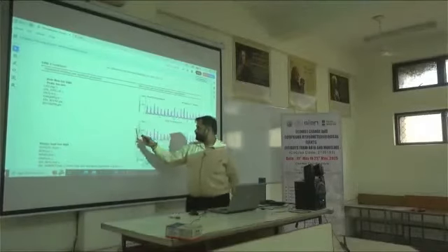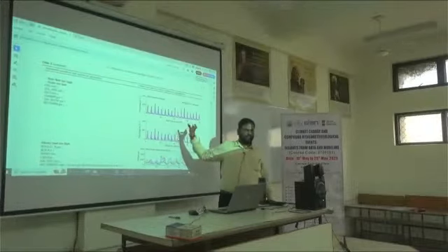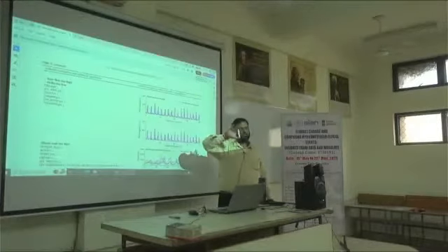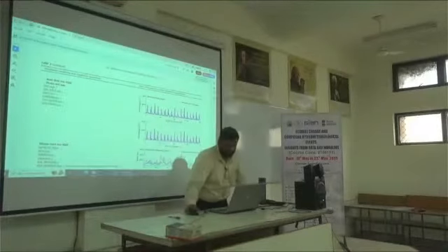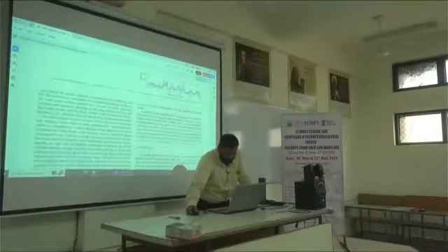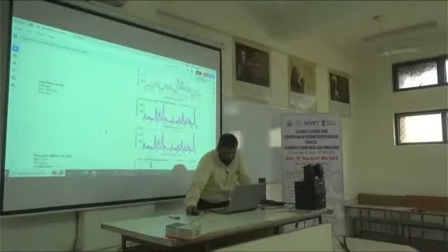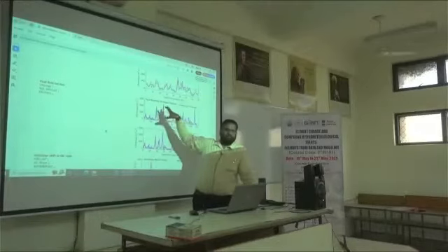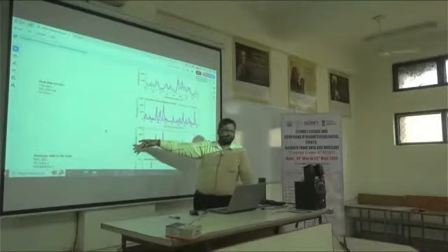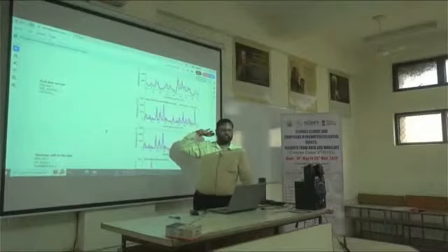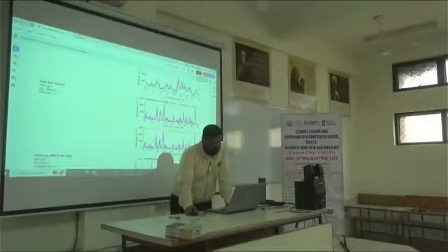If you are getting these types of results, that is why I am saying before going to SWAT-CUP you have to analyze your data in Excel only. Then you can easily identify which type of parameters you have to adjust. So that is the best paper which you can refer to for calibration and all these things. All the scenarios are given, whether you have to increase the curve number or soil water content, or ESCO, HRU slope, Manning's n, overland flow and everything. Again, they have also talked about P-factor and R-factor in this field.